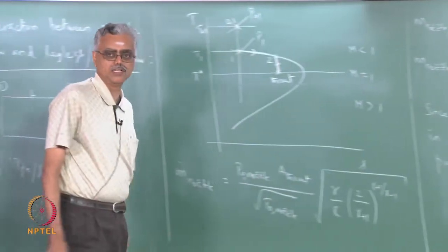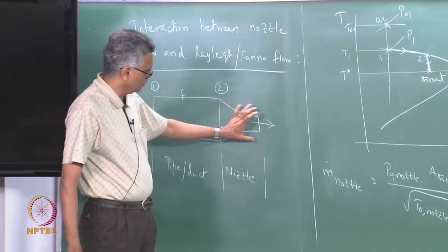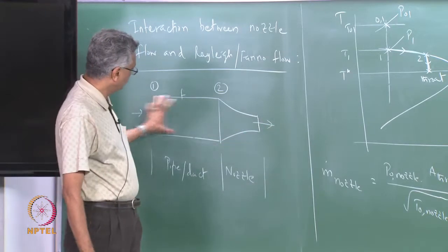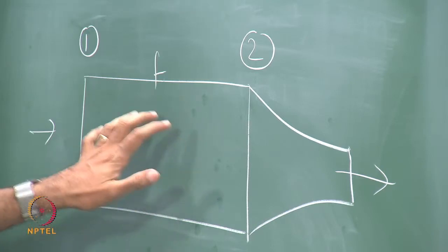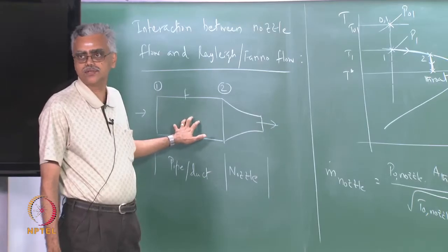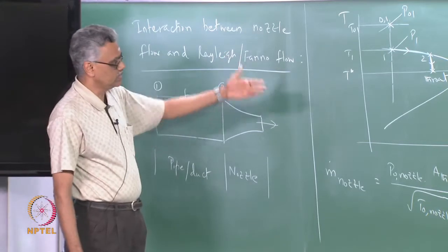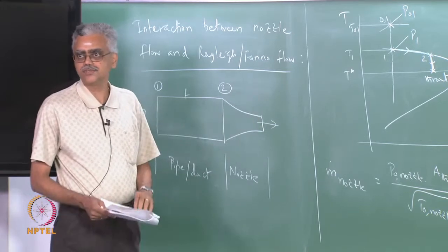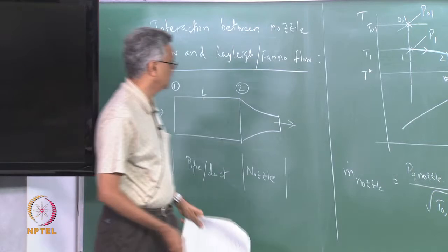And the reduction in mass flow rate, of course, is also another important aspect in this. So, there is a reduction in the mass flow rate as a result of this. So, when you design a nozzle for a particular mass flow rate and stagnation pressure, and if you connect it to a reservoir, you need to take this effect into account, the reduction of mass flow rate as a result of this, okay. We will illustrate these concepts also using numerical values once we complete the discussion of the theory. So, this is one situation. The second situation is the following.